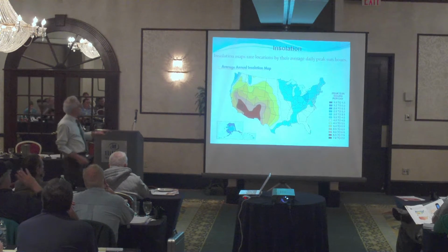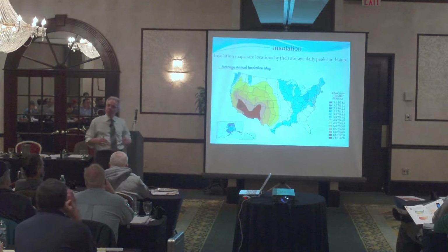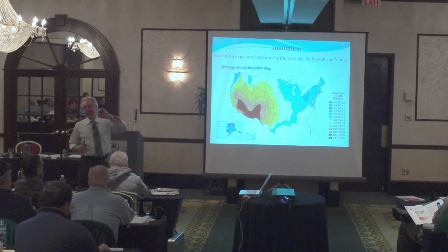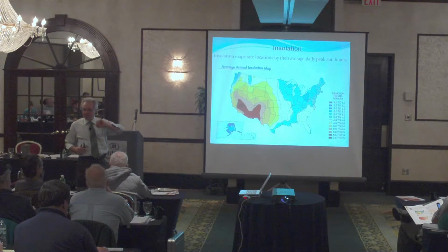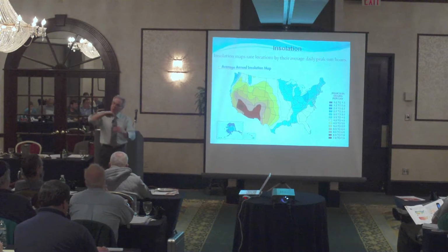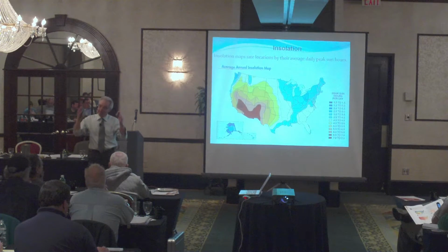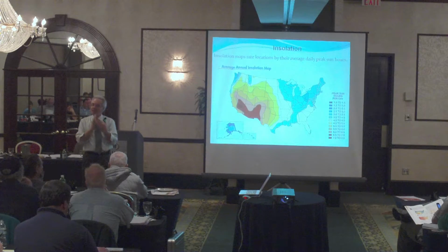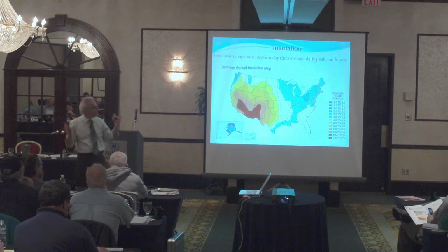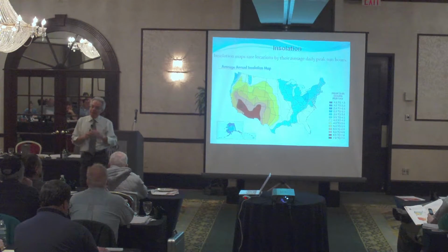No. This is the average number of peak sun hours, assuming that you get 1,000 watts per square meter insolation. Remember, over the period of a day, the amount of solar radiation varies. So you take that number, compile it, and divide it by 1,000 because that is the reference point we have, and then we come out with how many hours per day, how many peak hours I have. A peak hour is considered 1,000 watts per square meter.